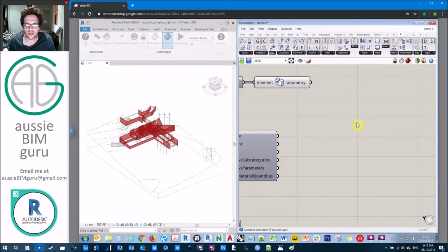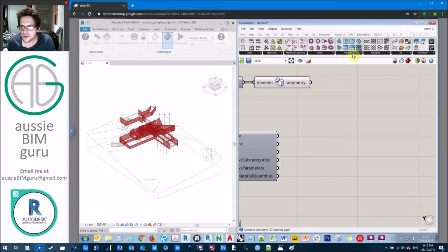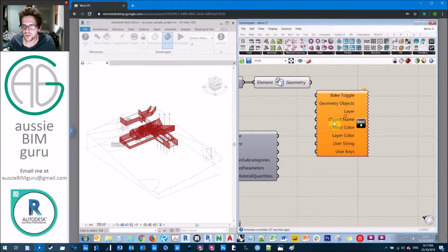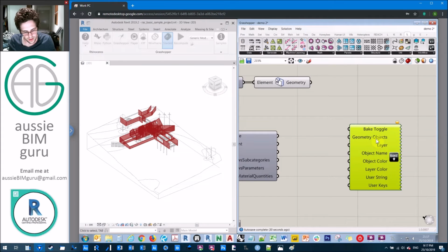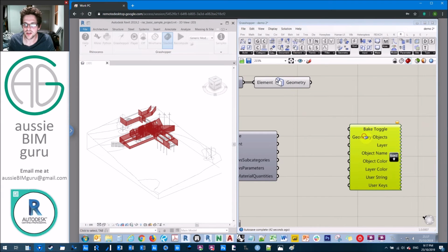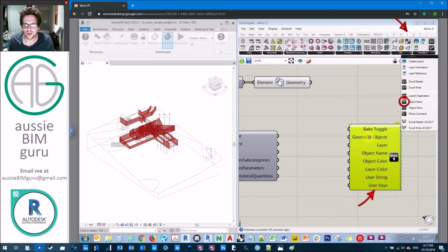When I want to bake things on a specific layer in Grasshopper, I use something from the package Lunchbox. I believe Lunchbox is here, and it's a node called Object Bake. So I might just find it in here and then find it in the ribbon. I'll get Object Bake, and I'll just go Control Alt Select, and it's under Lunchbox, under Workflow. There we go. That's a really handy tip. Control Alt Select on a left click and hold will tell you where a tool comes from. So really easy, especially for Rhino Inside, where you might not know where tools come from.